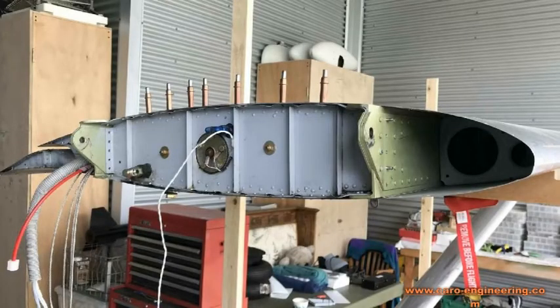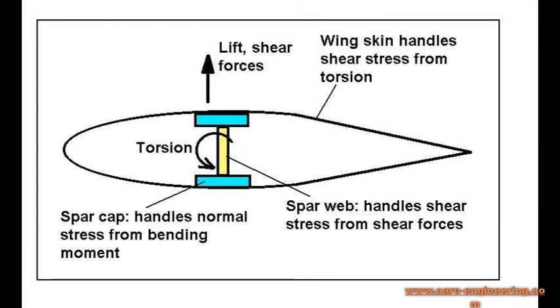Metal and composite wings used stressed skins for this job. A fabric skin is not counted as stressed. A single spar by itself can typically handle very little of the torque that the wing is subjected to. Because only closed profiles are torsionally stiff structures, we can either add a D-section leading edge from the spar forward or use the whole airfoil cross-section by extending the skin to the trailing edge. All the structural elements and what they are needed for are shown in this sketch.